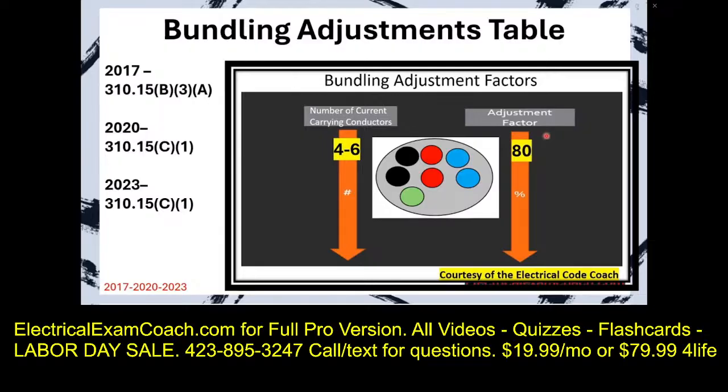Let's imagine we have a wire that's 50 amps. We take that 50 amp wire and we multiply it by 0.80, which was our demand factor. And we end up with a wire that is now only good for 40 amps.